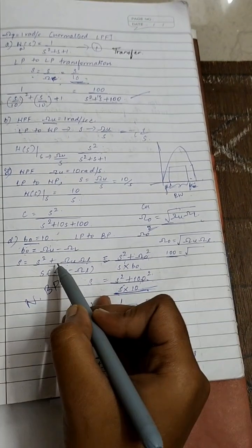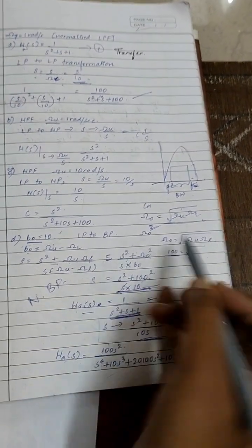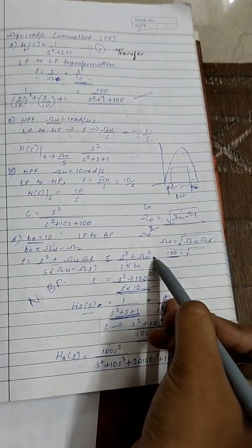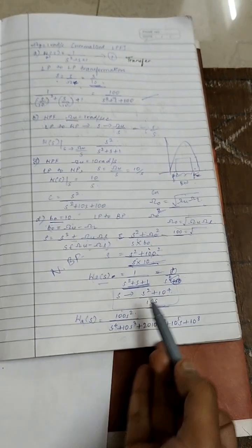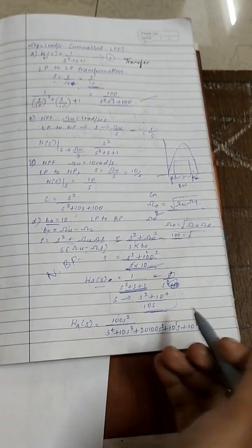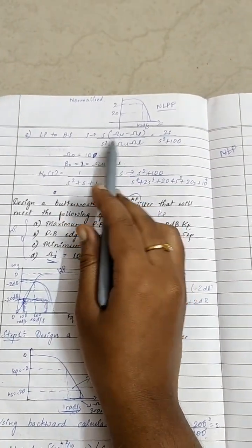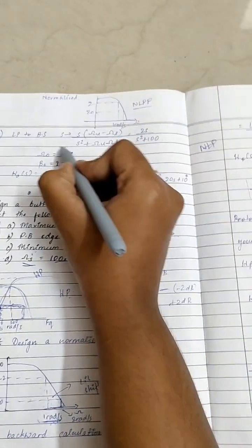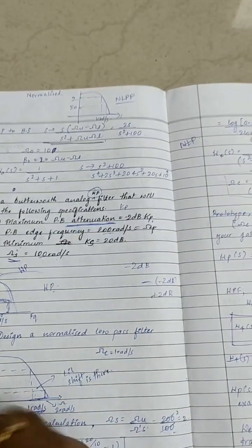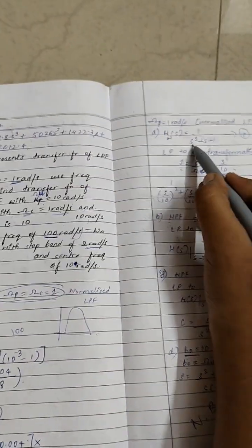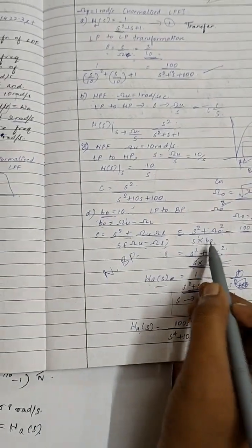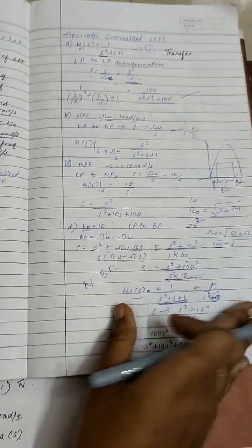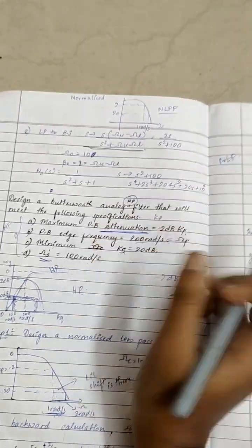Okay, so this s square, write it as it is. Omega u omega l, you already know from this formula, that is omega naught square. Omega u minus omega l is b naught. You have been given all these values, you substitute and you find the values. That's it. Then for band stop also, you have a formula, that is in place of s, you have to substitute this long thing. Where you have to substitute this, you have to substitute in this equation, in this place of s. Here also, this s, this part is there, no? This should be substituted here. All those values will be given, you can directly substitute and find the answer.